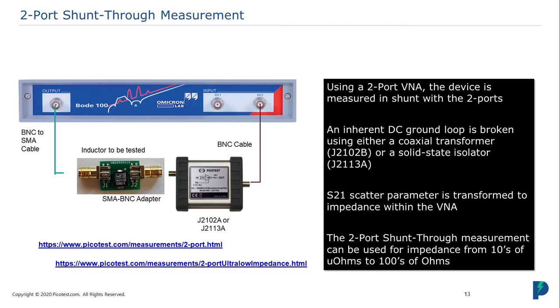This measurement setup can measure down as low as tens of microohms and up as high as hundreds of ohms, so it works really well for measuring low value inductors. And the impedance transformation is built into the software, so the software converts this directly into impedance and inductance.